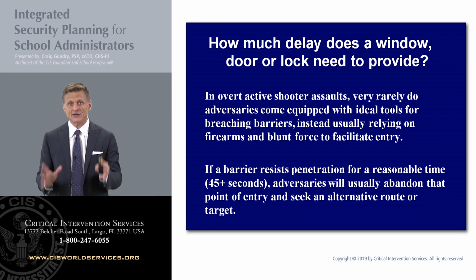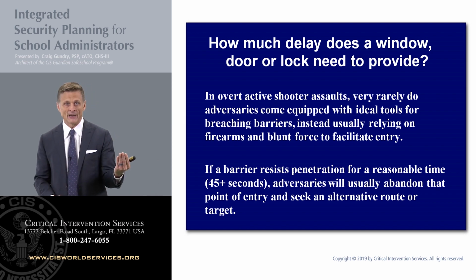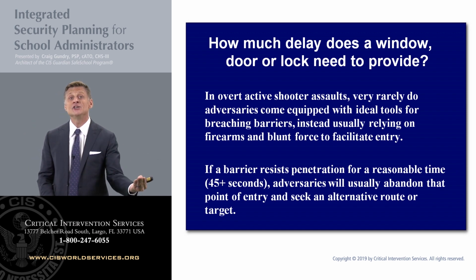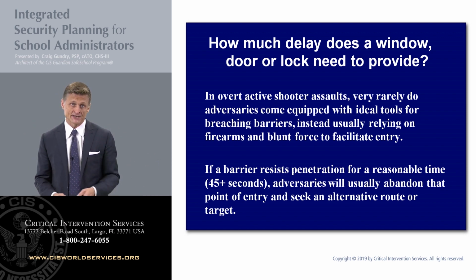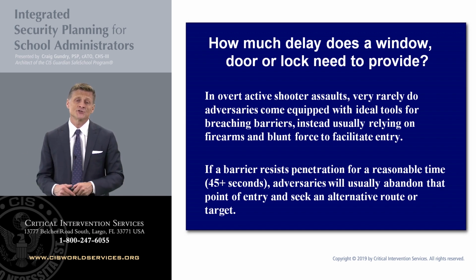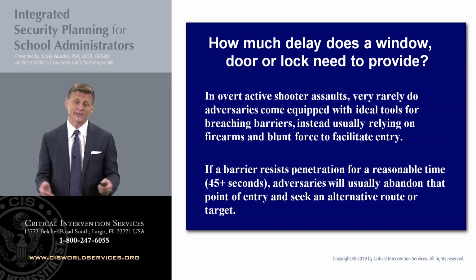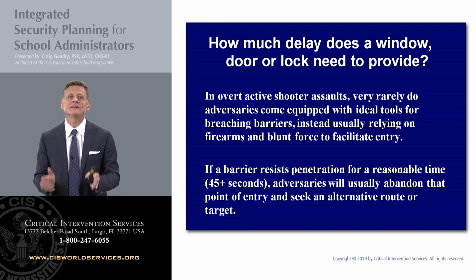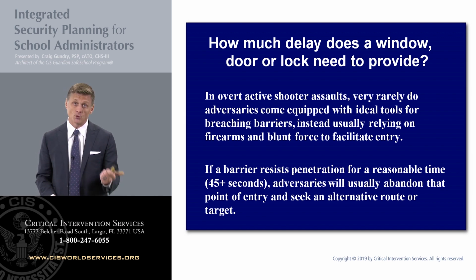Quite often, when we study the behavior of attackers in these situations, if they can't make entry within that time period, 45 seconds, they will usually abandon that particular barrier, that door, window, whatever it is, and continue moving in search of a more easily accessible target. That observation was also made by Smith and Renfro in an article they wrote on physical security and building design on the World Building Design Guide online. They made the exact same observation that quite frequently adversaries will not commit significant effort to breach particular barriers, instead recognizing that the clock is working against them on response, looking for easy targets.